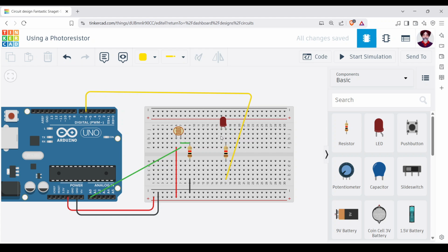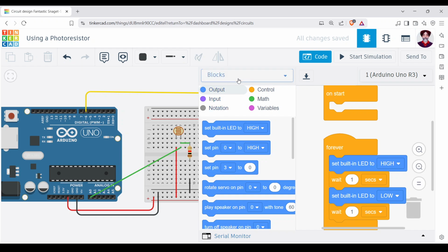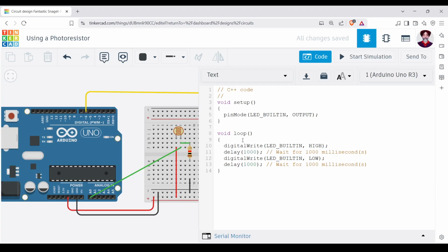The negative side of the LED is connected to ground. So let us connect it. This is how you would basically connect anything using an LDR or a photoresistor, a load. Okay, we'll connect another load in a few minutes. Don't worry about that. But let us now see how to program it. We are using two pins. We are using A0 and we are using a PWM pin. That is number 6. Let us see now how things should happen.